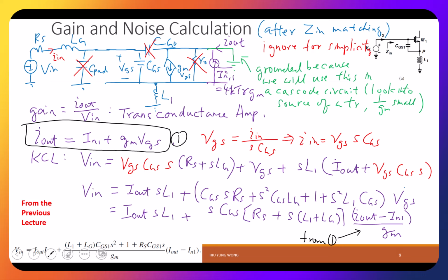And of course you should know how to draw the noise, right? For the transistor, there are 3 types of noise in a transistor. What are they? Thermal, flicker, and shot, but we don't talk about shot. We have not discussed shot. But what I'm more to say is that one is the thermal noise from source to drain, another is flicker, another is the thermal noise due to the gate resistance. But usually for a well-designed transistor, that should be small, right? So we usually ignore it, and in almost every problem I say we also ignore flicker noise. Actually, it is wrong to ignore them, but I just want to make things simple, right? So I have 3 noise.